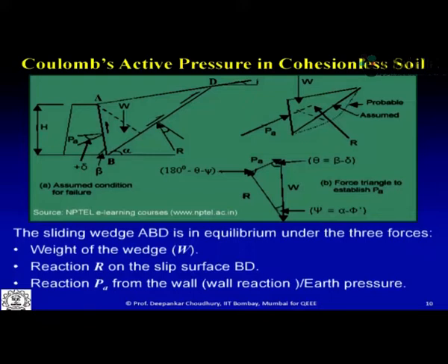So here you can have an inclined surface of the wall, and this angle is called the wall friction angle. That is the friction between this wall material and this backfill soil material. So that's why some frictional force develops over here. If you take a normal to this wall surface, with respect to that normal, your active earth pressure will act at an angle of delta inclination, which is marked over here as positive delta. I will explain that also in a little while, what positive delta or positive wall friction angle means.